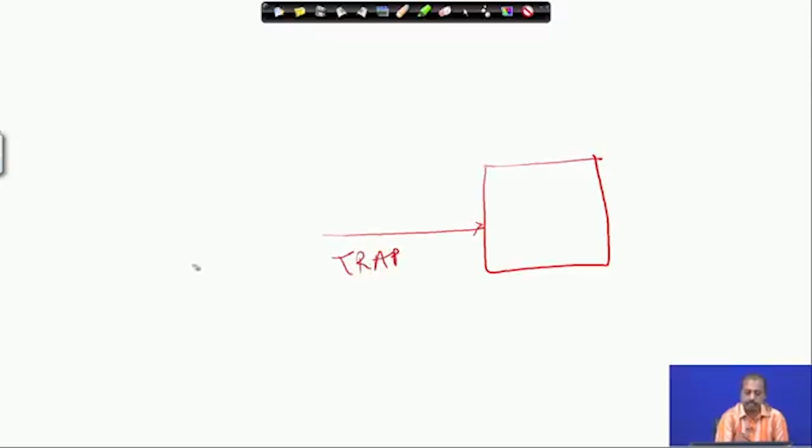So, what is required is that there will be an edge followed by this level. There will be some minimum duration for which the signal should remain high. So, this edge should be there plus this level should be there. It will be sensed only if both of them are there. So, this makes it slightly different compared to the simple edge sensitive and the level sensitive interrupts. Level sensitive interrupts need to be turned on for quite some time, and edge means that any activity occurring will get sensed.